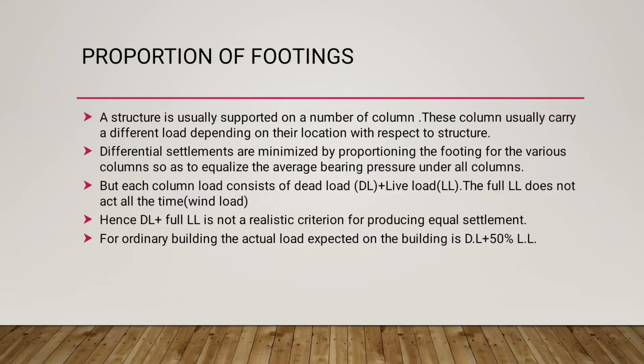So first one is proportioning of footing. Normally the structure is supported with a number of columns. These columns carry different loads depending upon their location, their sizes, etc. By proportioning of footing, the differential settlements are minimized so that they equalize the average bearing pressure under all